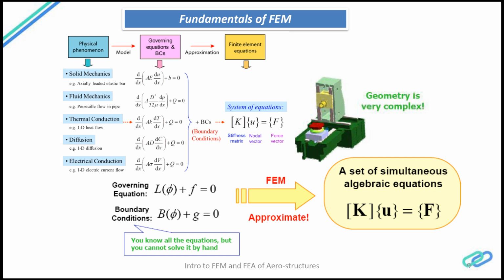It depends on the set of criteria, and then once the boundary conditions are assigned, these differential equations are converted into a set of algebraic equations. There are some techniques that convert the governing differential equations into a set of algebraic equations, and finally the algebraic equations are solved using the matrix method. So it combines the polynomial equation of the field quantity, and at the same time it uses the direct stiffness matrix method.